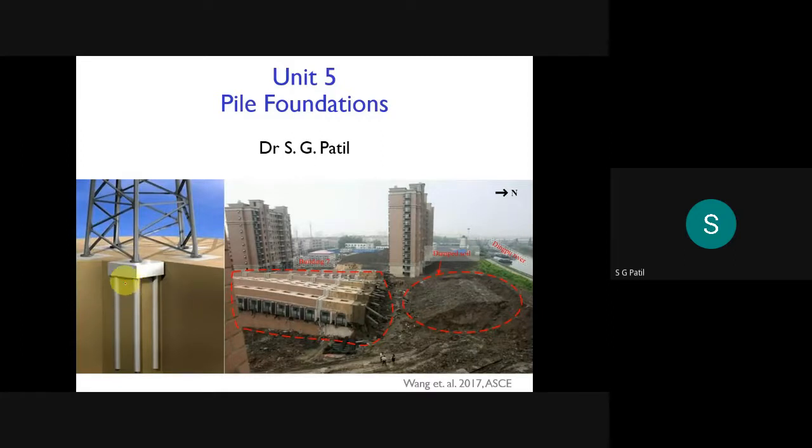So these pile foundations come under the category of deep foundations. When you go for a deep foundation, if you have very poor soil in the shallow region, maybe within 2 to 3 meters, then you will think of a pile foundation. But if the poor soil is only 2 to 3 meters deep, usually you will remove that soil, replace it with some good soil and compact it well, and then you can go for shallow foundations, provided your loads are small.